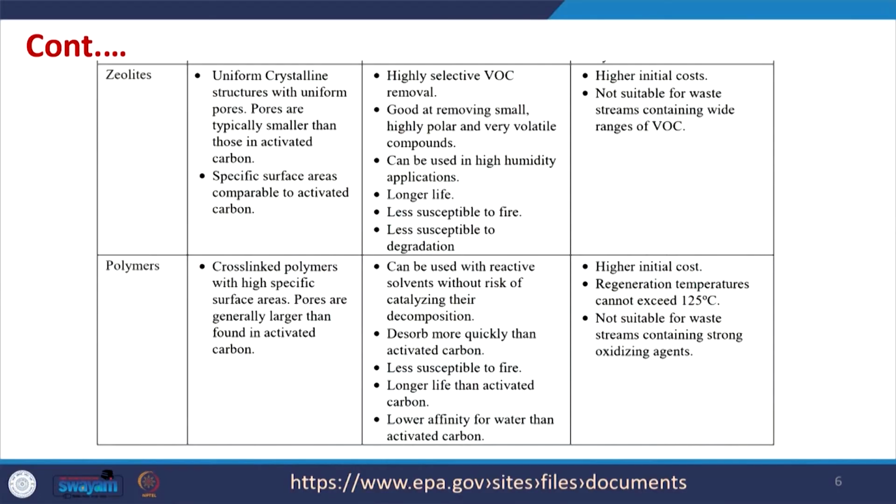everywhere. Similarly, zeolites etc. are also very common, and the good thing with zeolite is that they have a very uniform crystallite size structure with very uniform pores. So, that means if they have very uniform pores, we can design the pore size also, okay, and that is how we can select a zeolite with different pore sizes. So, if suppose we have a stream which is having molecules of different size ranges, we can easily separate them out using zeolites of different pore sizes.